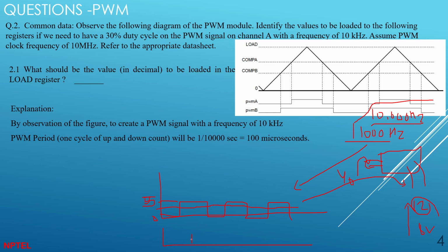And suppose you want to reduce the duty cycle to, let's say, 30%. This is what the signal looks like, and instead of giving 2.5 volt here, it will give somewhat around 1 volt. Basically, at the end of the day, we want to give the motor an analog signal, meaning minus 12 volt here, plus 12 volt there, or plus 8 volt here, minus 8 volt there.